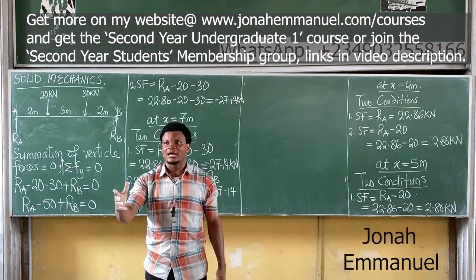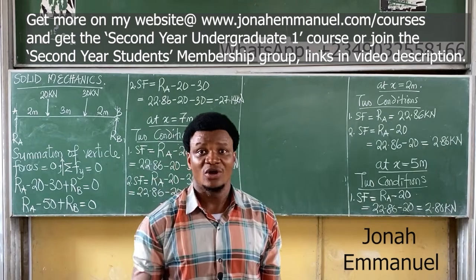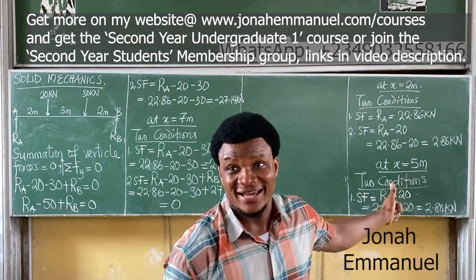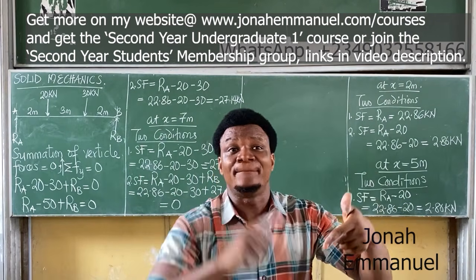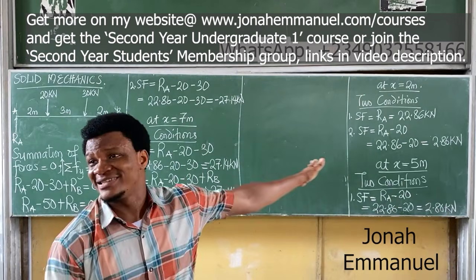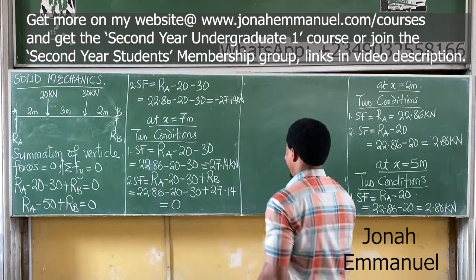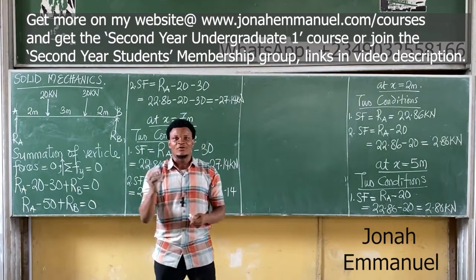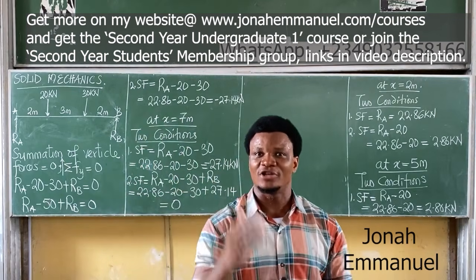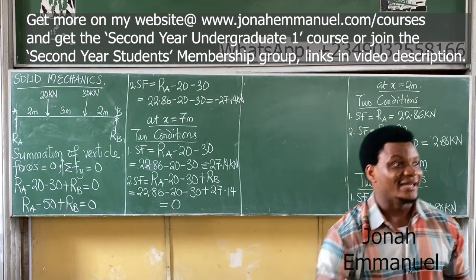I'm done with the shear force calculation. The second calculation is now what? Bending moment calculation. All of these things are for one question, and we've not even drawn the diagram. These are pre-diagram calculations. Is this still easy for you? Check your past questions and you'll see. All right, so you get your value of reactions, RA, RB. When you're done, you do the shear force calculation. When you're done, you do the bending moment calculation. When you're done, you then draw the diagram.